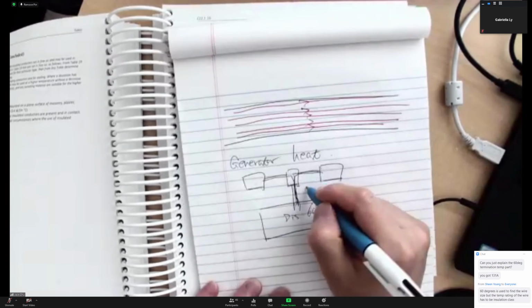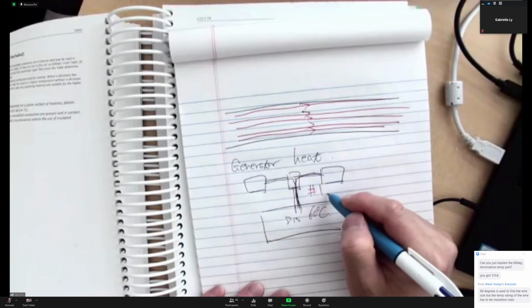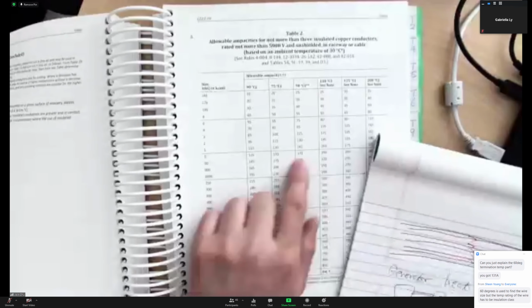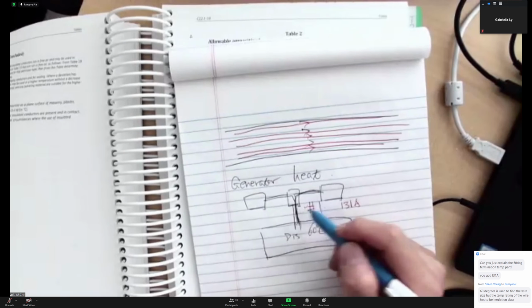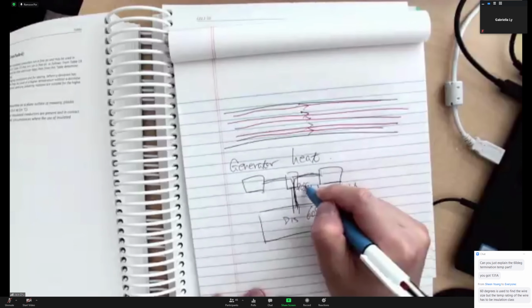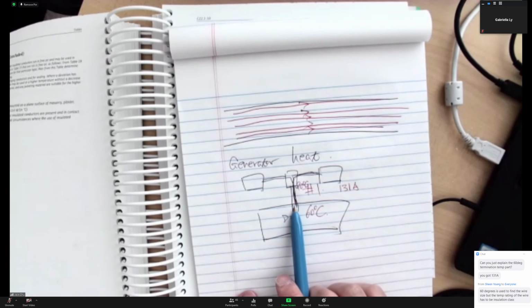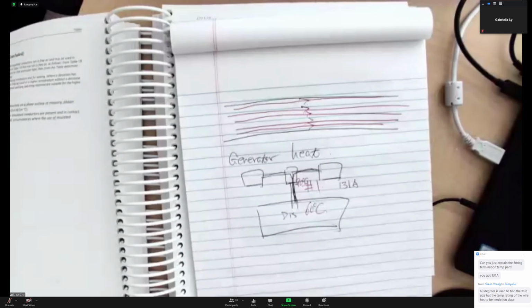But if I just use the number one conductor in here, the number one to carry 131 amps, right? The temperature of the conductor will reach almost 90 degrees. If you reach 90 degrees, are you allowed to go into this distribution panel? You're going to damage it.